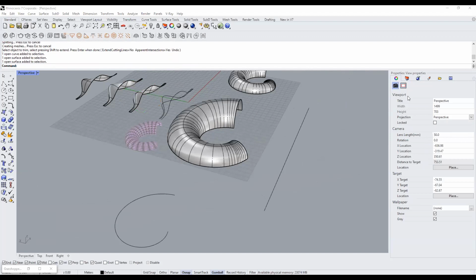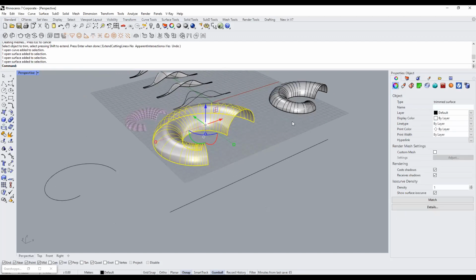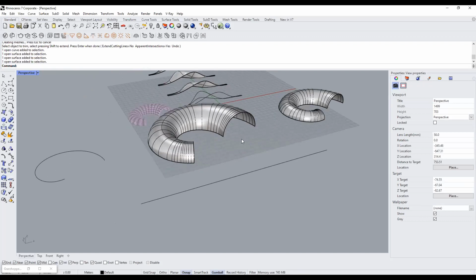Can't delete the opening surface of the tube. Also, the spiral command has a lot of curves. You need to check for 2 things. Opening, you need to explode it first. You might have missed the explode step. After you explode, you can delete off the front faces.